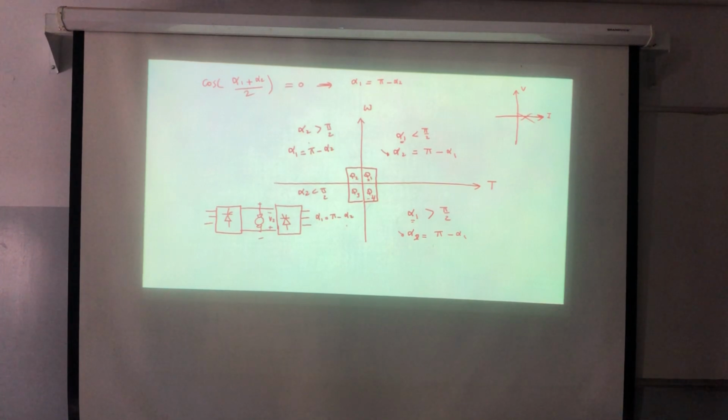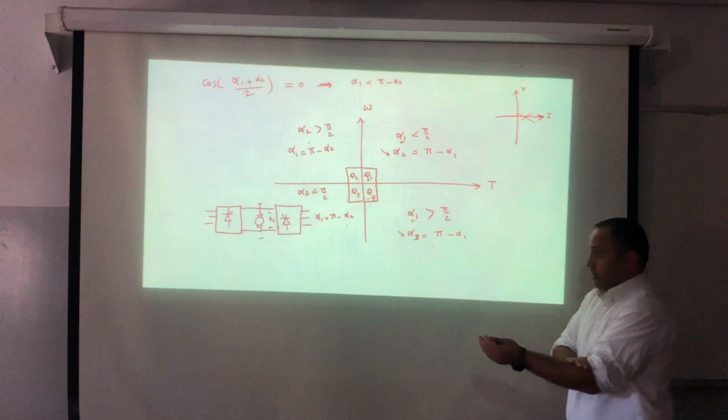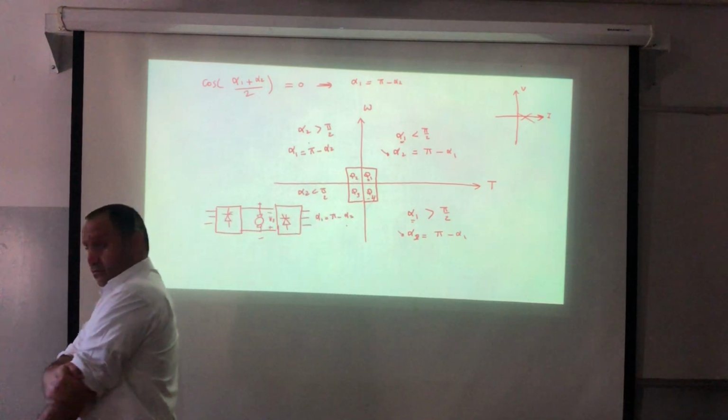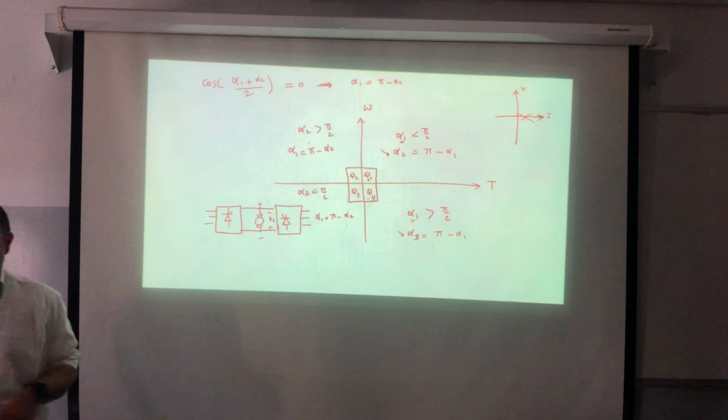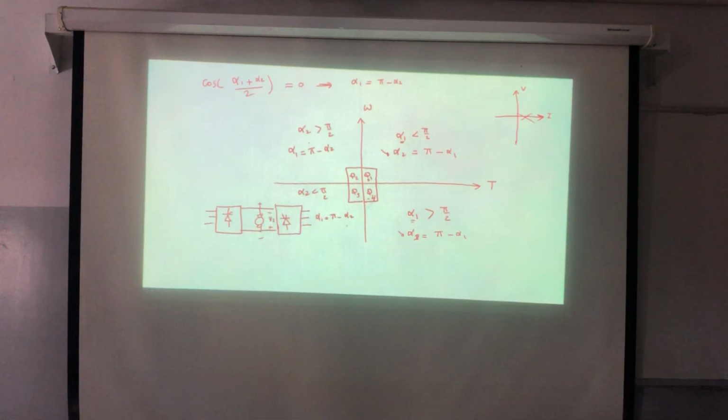Now, what about this four mode of operation? Can I support the four mode of operation using only one converter? Are you sure? Of course, I will reconfigure the converter. Really? How? So I will connect the load between the midpoints. In this case, I can now have the two ways for the current flow. So this also can be done with an H-bridge.